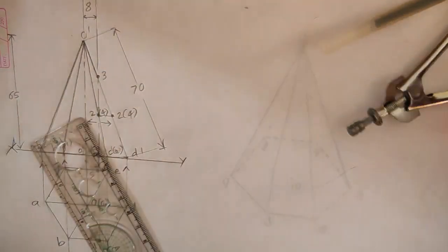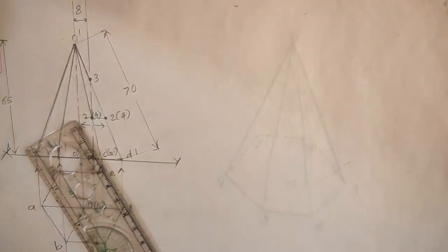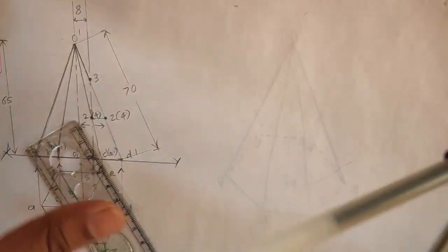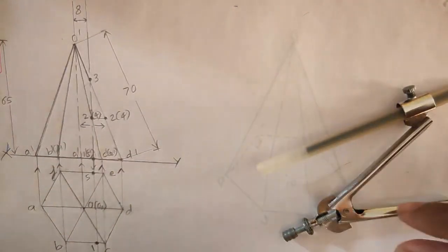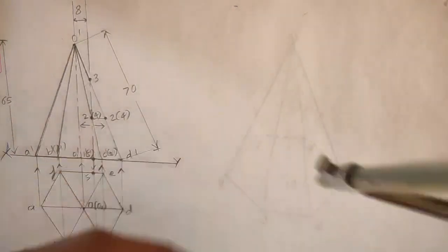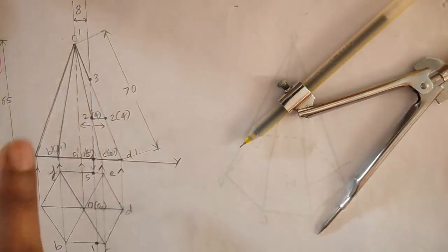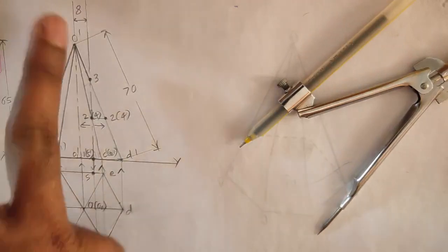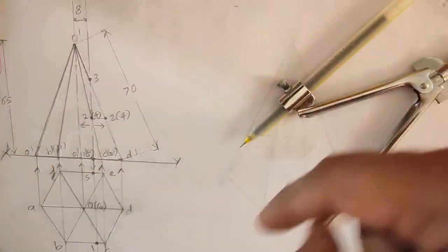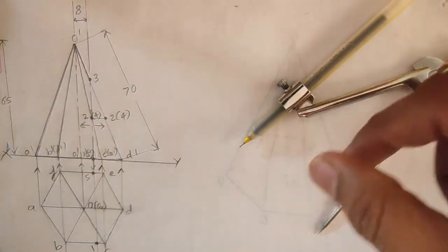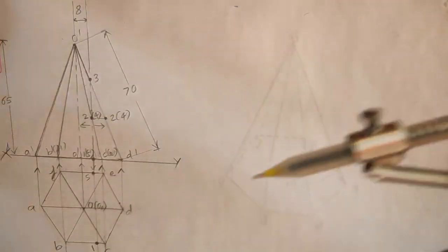So this is going to be helpful for me to make the development of lateral surface for the entire pyramid. So you know the process to do that. If you cut open a pyramid at, say, OA, and if you spread it, you'll get 6 triangles. So you need to draw the 6 triangles first. I'll show you how that is done.